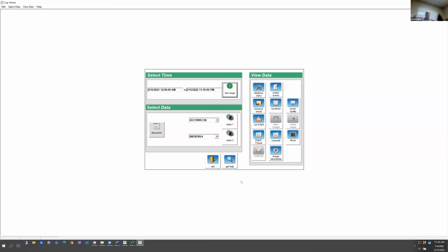If you're using Nexus meters, you can also get some power quality reports that are automatically generated. And this is what you would get in addition to the flicker. You'll get the reports on harmonics, voltage sag surge, short interruptions, long interruptions, and data like that. And we could cover that. That's a detailed meeting on its own. So I just want to stop right here.